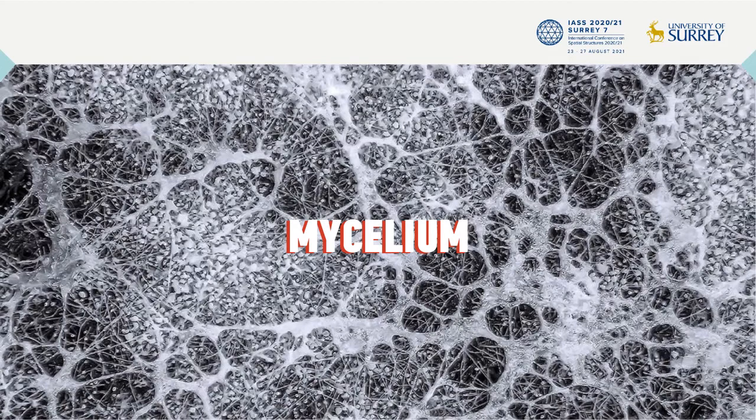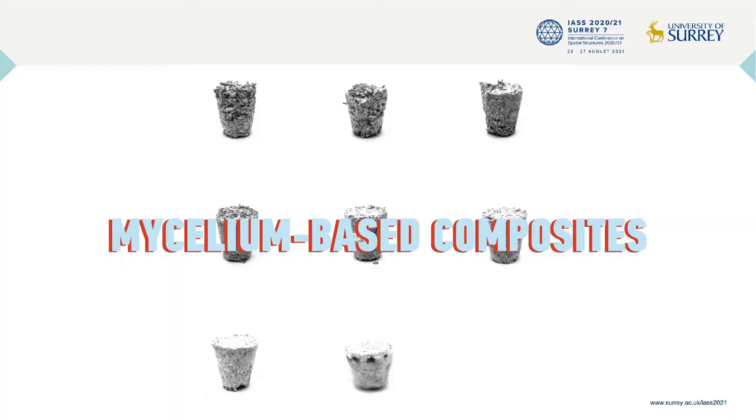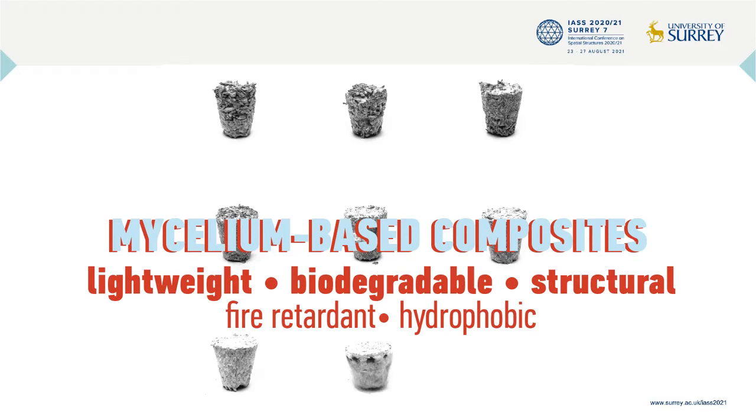Mycelium is the vegetative root of fungi which decomposes organic matter for absorption of nutrients. In this process, mycelium bonds the organic matter together. The incomplete decomposition results in a foam-like material, the mycelium-based composite. This composite is lightweight, biodegradable, and a structural material that works best under compression.